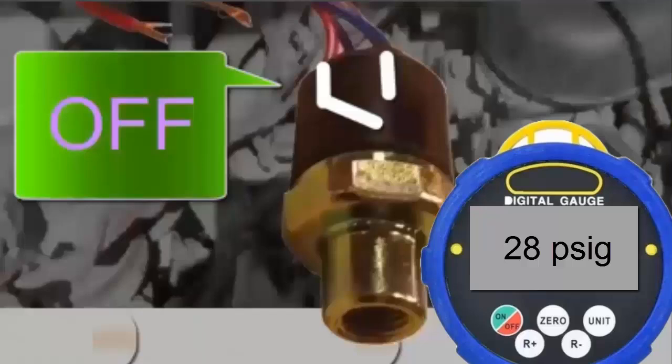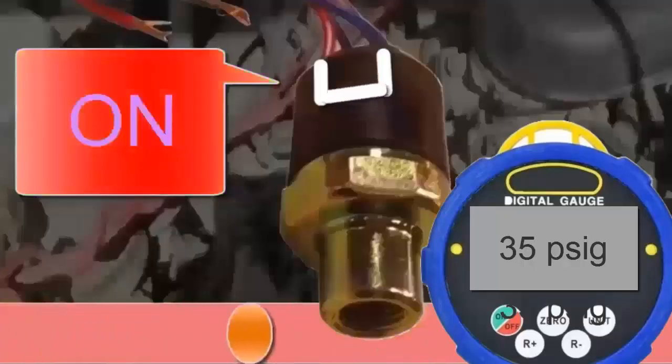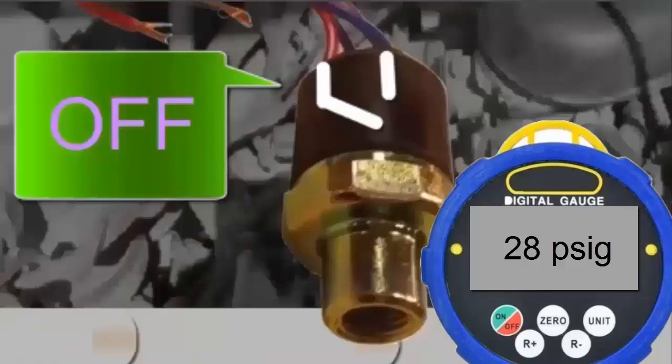For example, the normal operating pressure with our 134A refrigerant should be approximately 35 psi, pounds per square inch. If the pressure drops below 28 psi, the low-pressure switch functions as a circuit breaker, disconnecting the compressor to prevent potential system issues.